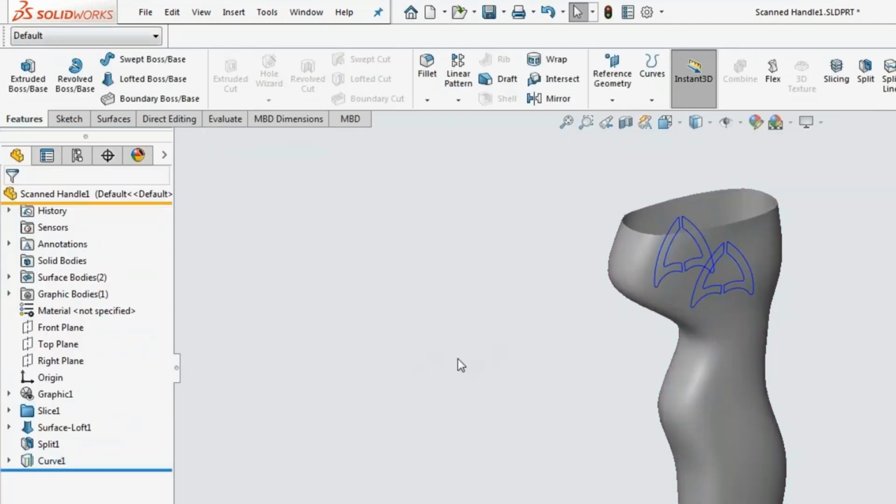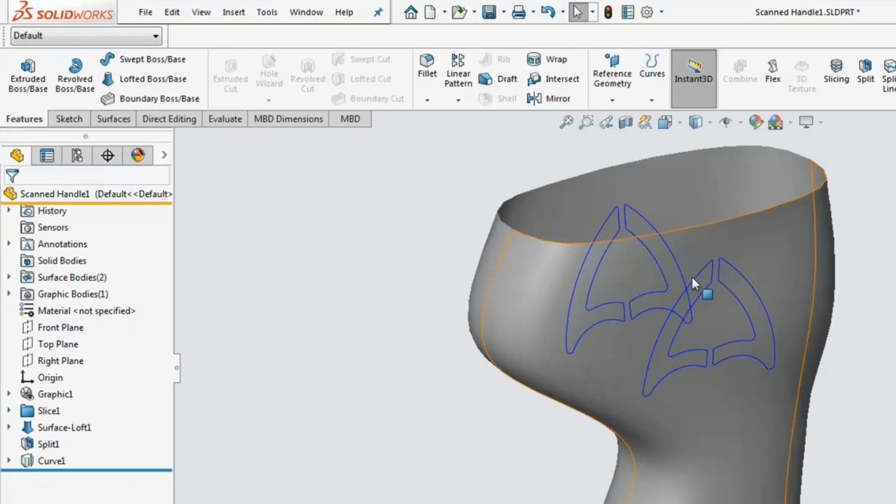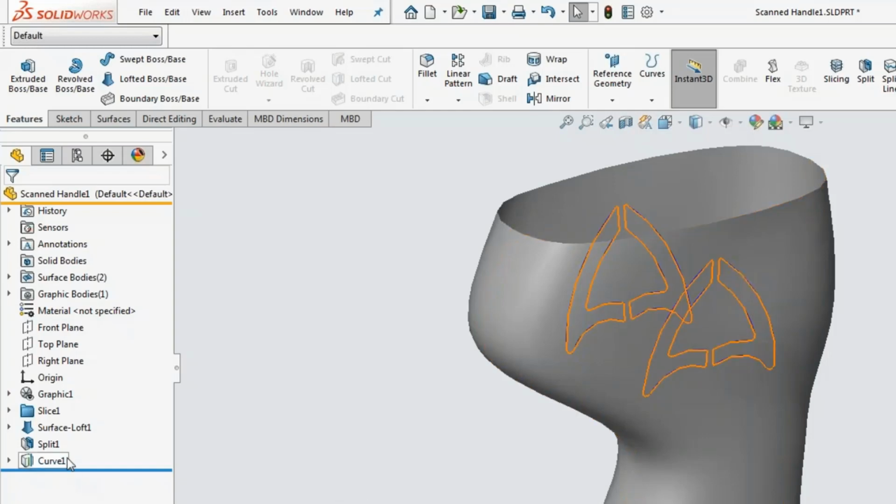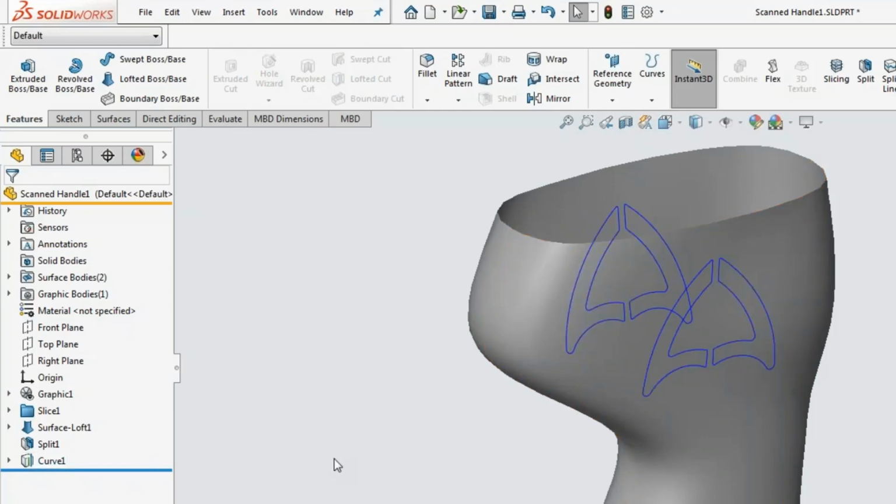Now the advantage of this over what we had in previous years is that this sketch is actually two disjoint sketches. So in 2019 you can use open or closed contours that you have multiple ones of in one sketch, and you can use them on multiple faces. So whereas this is one feature, in previous years this would be 4 features. So it makes it a lot faster to manipulate your model and make the design changes that you want.